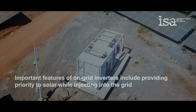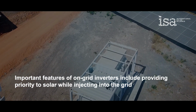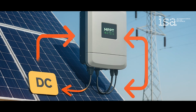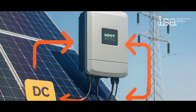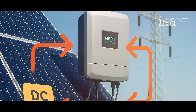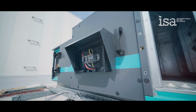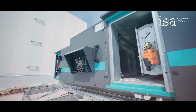Important features of on-grid inverters include providing priority to solar while injecting into the grid, controlling harmonics and maintaining grid stability, operating maximum power point tracking, MPPT, to maximize use of available solar energy, and providing anti-islanding protection. As already mentioned, the on-grid inverter can synchronize with a diesel generator supply as well as the utility grid.